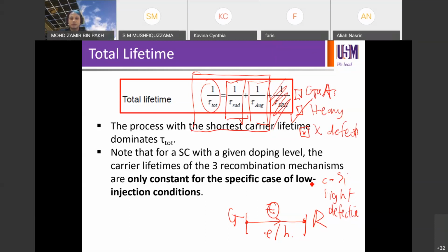Okay, so it's crystalline silicon, direct or indirect band gap? Indirect, right, so therefore the radiative is not dominant. Okay, so we can cut radiative. Then Auger, is it lightly doped? It's lowly doped, right? Or lightly doped. Therefore, there's no Auger component. So we only have, now we are left with full of defects, right? Only. So the dominance is actually relative.